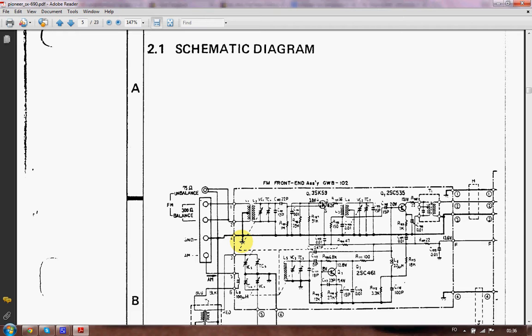Unless of course you want to measure specific voltage drops across some components or something else. But one of the key factors I like to exploit when trying to repair is given voltages in the diagram. And the given voltages are always going to be direct current, unless they're on the primary side of the coil before they're rectified from your household socket.